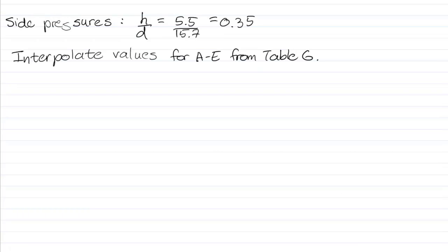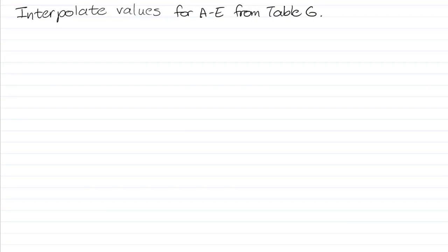Now, there's another requirement in the code in terms of lack of correlation between the windward and leeward wall. I'm just going to do a sketch on the side here so you know where this comes from. If you have a building, the pressures are constantly fluctuating.